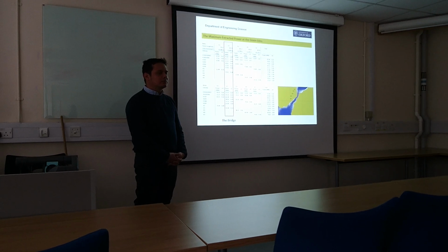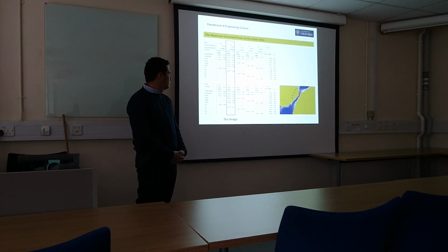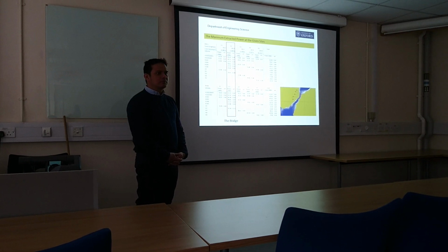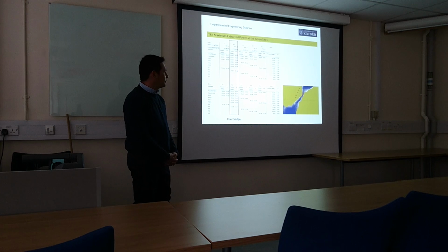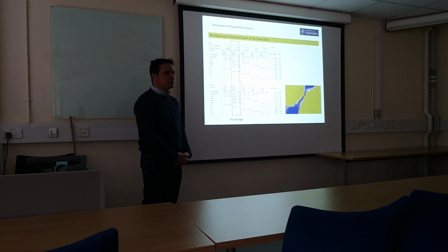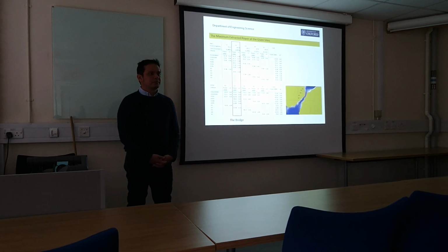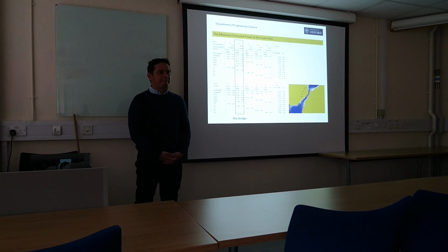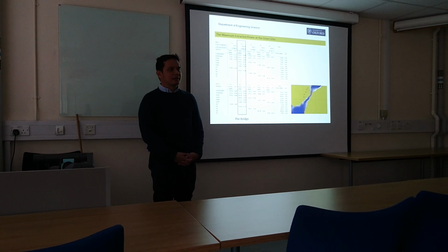And then you try to put them all in and you get that row A1, A2, A3, A4, A5, and the 74 has gone down to 18. It's only 25%. So if you have low blockage ratio turbines, you can put them upstream and downstream, because you're not taking out all the resource. But if you have high blockage ratio, it's no good. Yes. There's no point having another row of high blockage ratio.